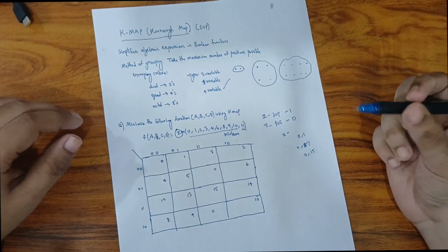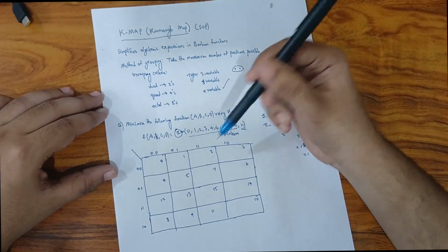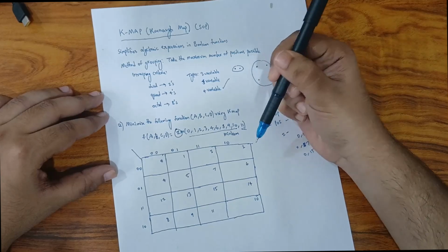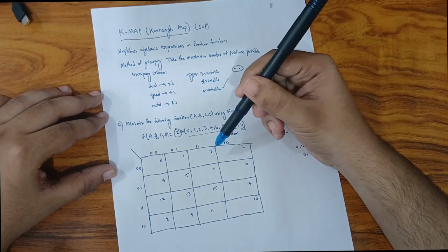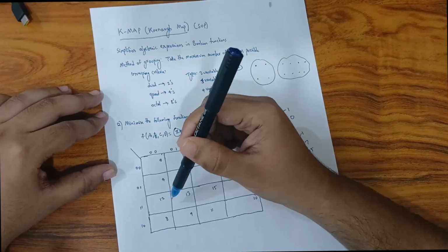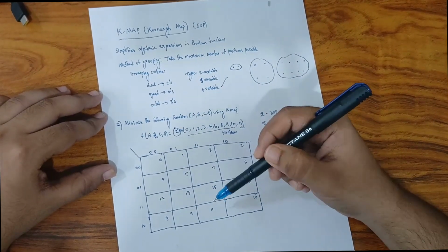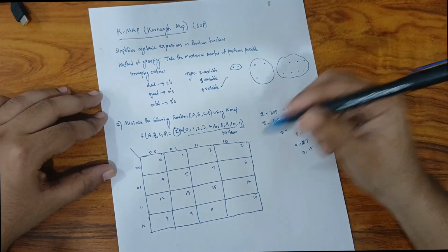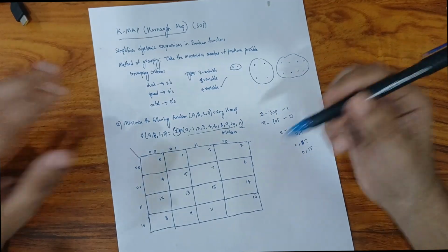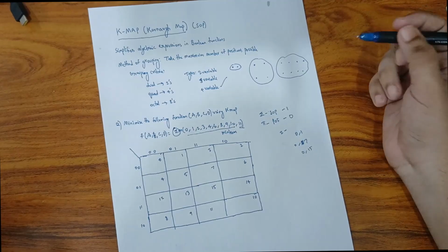I think you observed some kind of trend. In the second row, the last term comes first, so you can see some swapping, and in the fourth row you can see that we swap these things out. This is how we write a K-map. This is our positioning for the 16-cell four variable K-map.